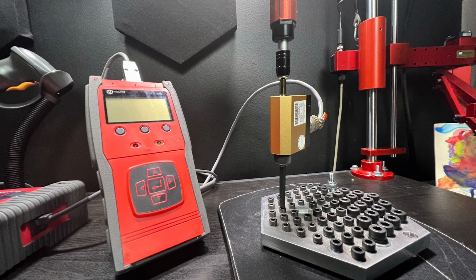And then we also have customers that will not base their calibration of a particular tool on time. They base it off of how that tool performs in that particular application. And so they will do this validation check at a certain frequency, and as long as the tool is still within the operational limits, then they continue to leave that tool on the floor and keep using it until it shows signs that it may be getting close to needing some adjustment or recalibration. And so the torque verification process can help you to extend that, and you are then collecting all of the data that is being used for that particular tool on that particular application.